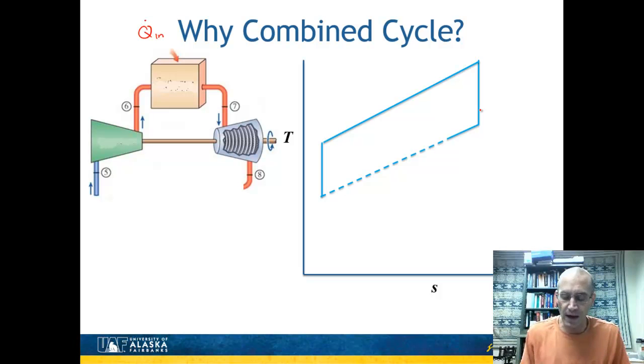These can operate at really high temperatures, at temperatures greater than, say, 1,000 degrees Celsius. And it's really just limited by the components of the turbine. And what that means is that these outlet temperatures, as I've shown over here, can still be really warm. And even if you're using a regenerator, you're still losing a lot of energy between this dashed line here. And so it sure would be nice if we could recoup some of that energy.